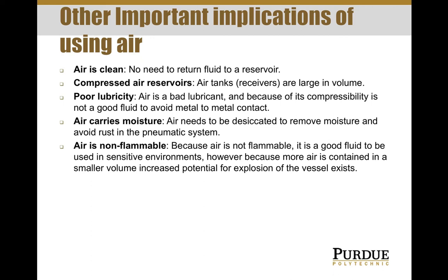Another thing is that air is a poor lubricant, and that's because of the same reason: it's compressible. So when you have two moving parts and air between those two moving parts, the compressibility of air will not suffice to separate those moving parts. It will just be metal to metal contact, without any air in between to impede that contact.